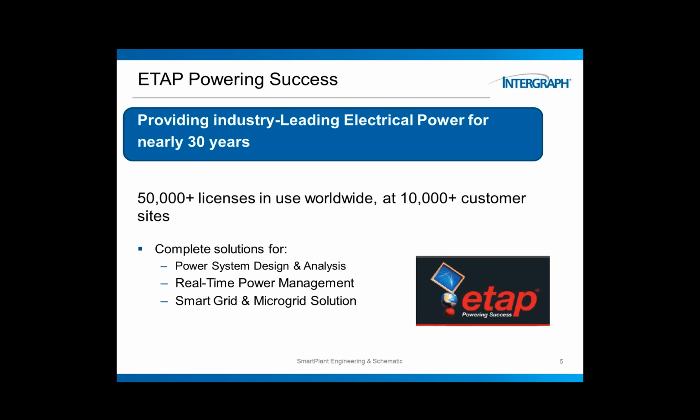That is the design and analysis of the solution. That is what I talked about earlier, when we can hook up SmartPlant Electrical and make sure the design is right in a bidirectional way. But they also do real-time power management, and that is cool for the owner-operator phase, where you can actually monitor, just like a DCS for instrumentation. This is actually a DCS for the electrical system, showing how the system is behaving, and it can also do some load shedding. If some loads are failing, you make sure that the critical loads stay up and running so your product is still being produced.